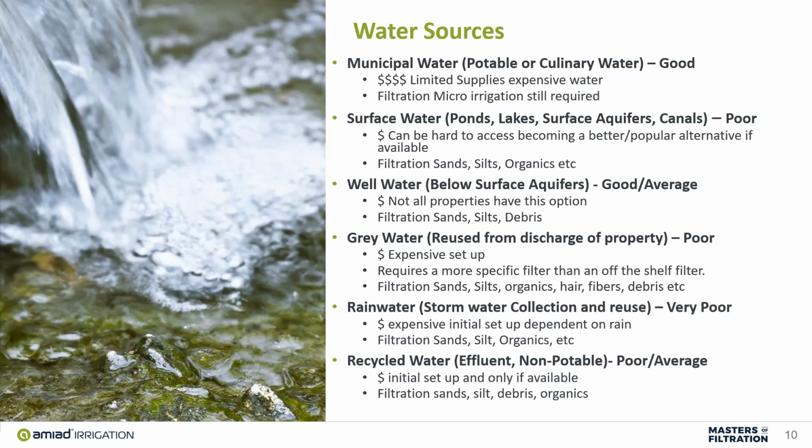Recycled water just ranges depending upon what district you're a part of. To be perfectly honest, there are some districts that actually have pretty clean recycled water that's distributed, and then some that's pretty dirty, and they run into challenges as they go. So again, we put a poor to average rating on that water. And these are our guesstimations on this water. It's important that if you're getting into detailed design requirements, as we talk, we'll go over those requirements that you're going to see. It's important for you to take the time to understand what's in the water before you put a specification out there for a particular filter to be used.